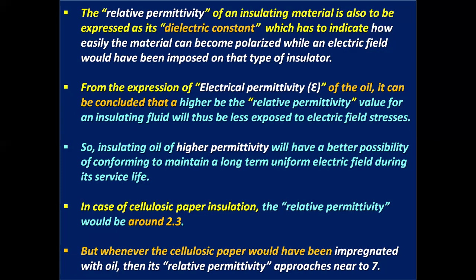From the expression of electrical permittivity epsilon of the oil, it can be concluded that the higher the relative permittivity value of an insulating fluid, the less exposed it will be to electric field stresses. So, insulating oil of higher permittivity will have a better possibility of maintaining a long-term uniform electric field during its service life.